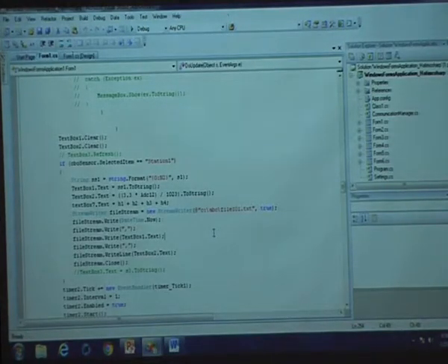Just a continuation of the steps here, we are able to get those ADC values converted to the corresponding temperature values, and now you need to write, if you want to store it in a particular file. Suppose I have given one file called file101.txt, an ordinary Notepad text editor file, where you can store the data.